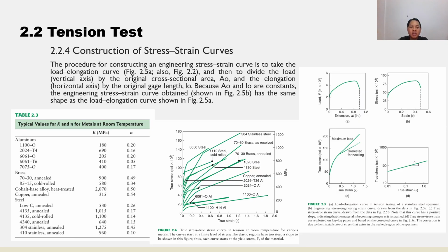Because A0 and L0 are constants, the engineering stress-strain curve obtained in Figure 2.5b has the same shape as the load-elongation curve in Figure 2.5a.